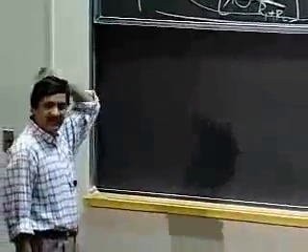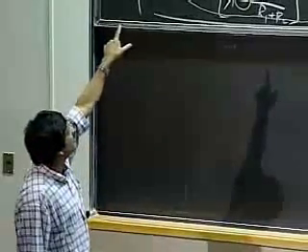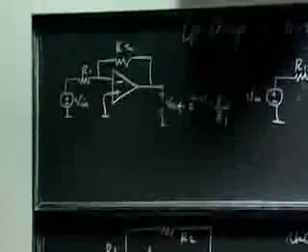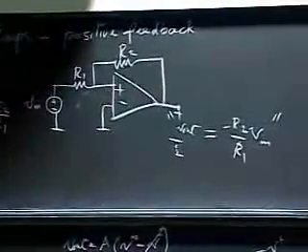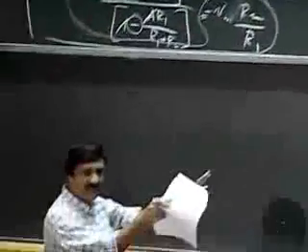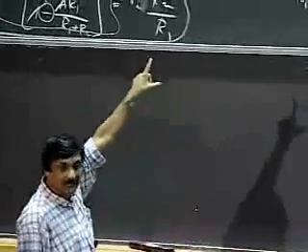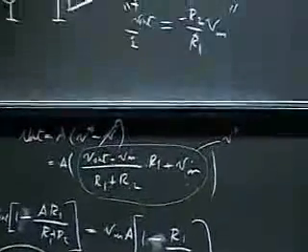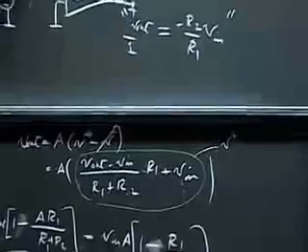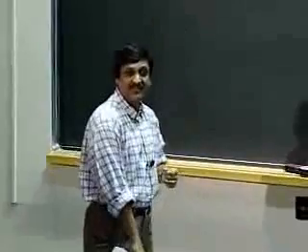So what we've done so far, if you stare at these two panels here, first of all, we know that the inverting amplifier has the expression for V out up there. And through this laborious exercise, we've also shown that even with positive feedback, if I take a static view of the circuit, if I take a snapshot of the circuit and simply analyze it as a static circuit, I get the same expression for V out. But what we're going to do is, I'll explain to you that, look, a small perturbation in V out is going to drive the op amp to the positive and negative rail.